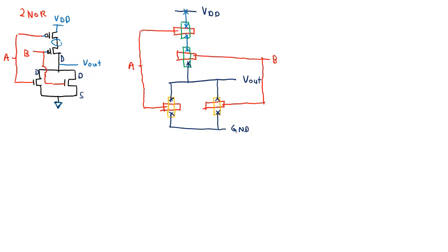You need to reduce the size. If you draw like this, you will take some space and area. So in order to optimize this, you need to rotate 90 degrees. Just rotate it. Maybe we start from the PMOS, the first one there. Rotate the polysilicon, becomes like this. Rotate the second polysilicon, becomes like this. And then we have the P diffusion. Rotate it, it becomes like this. And rotate that, becomes like this.